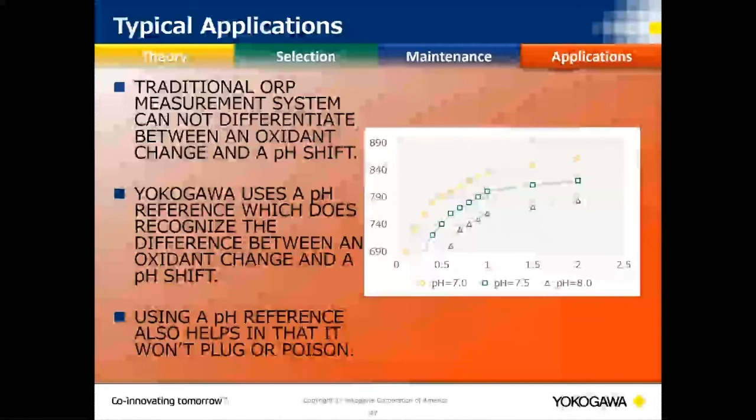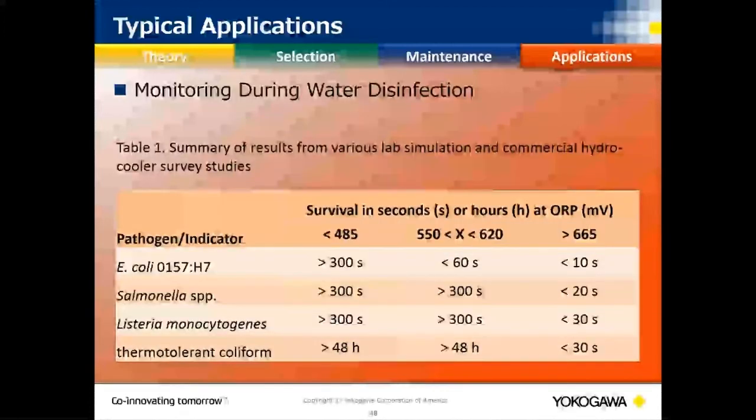And then this way, whenever I change my pH in my cooling tower, I know that the millivolt value I'm seeing because of my chlorine concentration is honestly because of the chlorine concentration, not because of a millivolt value associated with the pH change. So again, that chart that we referenced before, this is just common, what we've seen.